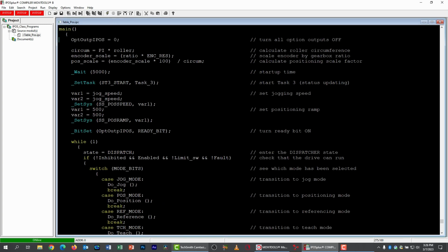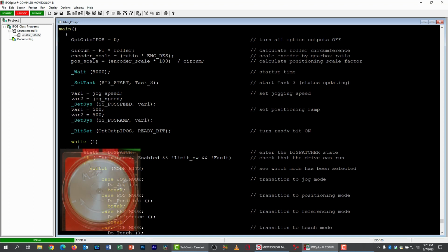and run it. The first thing we need to do is position our drive to some random location and then program it into the H9 location and check it out with the All Variables window. So what I'm going to do is really simple. I have my control box. The first thing I'm going to do is go to location 0. That is currently stored in the teach position. So that's kind of a home position at the moment. As soon as it arrives, we know where it's starting. And what I'm going to do then is jog it away from that location and then program it.